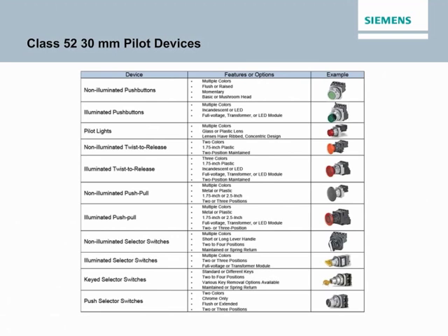Illuminated device options include traditional incandescent lights along with energy-saving LEDs and extra bright cluster LEDs. Ribbed concentric lenses improve lighting distribution and aesthetic appeal. Devices are oil and dust tight and meet NEMA Type 1, 3, 3R, 4, 4X, 12, and 13 specifications.